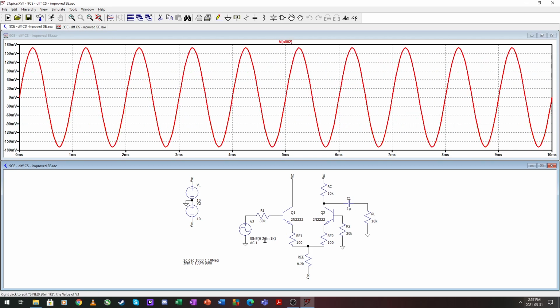And if we take 20 millivolts peak multiplied by 53, which is the gain, and then half due to the input loading and half due to the matched output, we get 165 millivolts peak output right here. So that confirms our 53 volts per volt gain for this amplifier. That's excluding our loading effects. So yeah, there is the single-ended conversion.